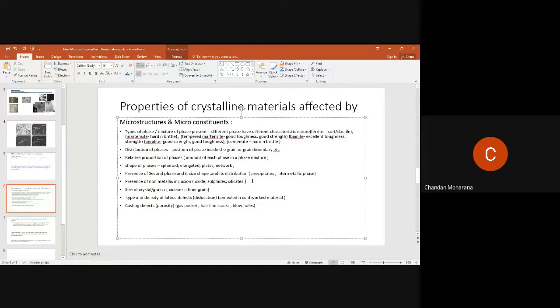Non-metallic inclusions are basically a very hard phase. Hard phase means they will not undergo deformation while you are deforming. So can anybody tell me, if non-metallic inclusions are there in a steel and you are deforming the steel, what will happen just around the non-metallic inclusions? Stress concentration will be more? Yes or no? Crack will...